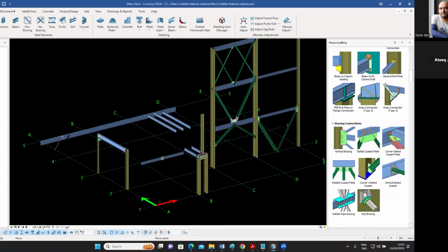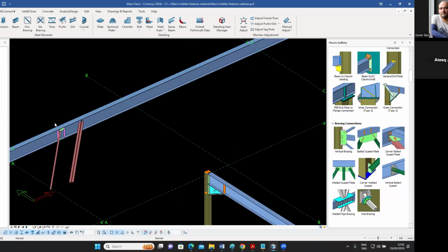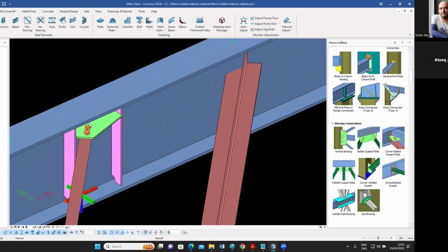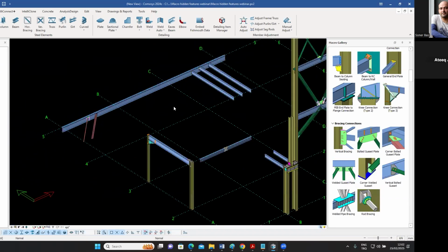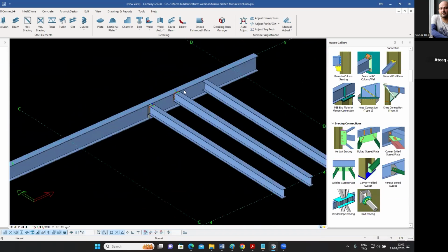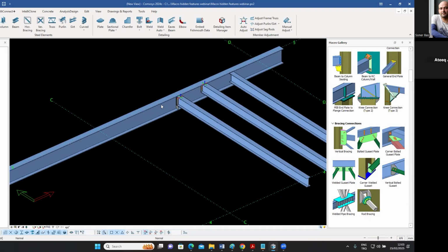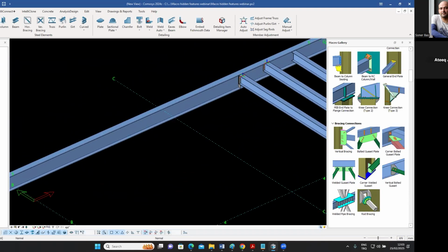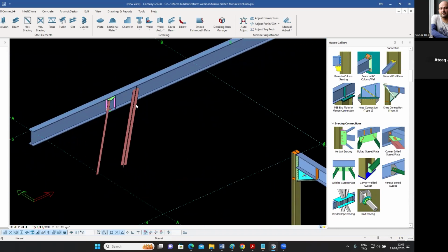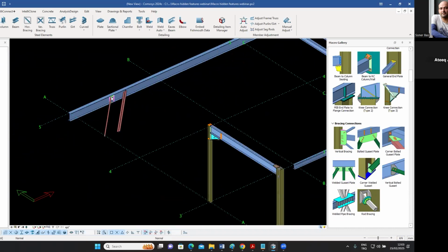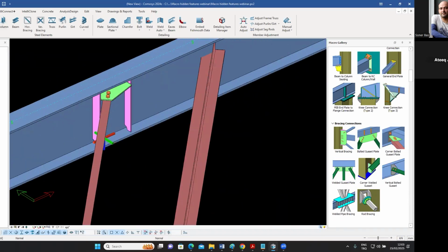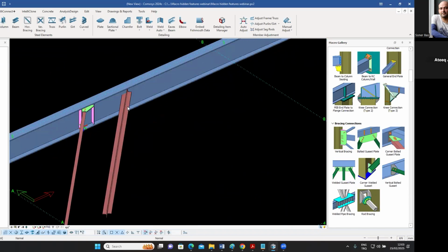So what did we talk about? We talked about the gauge lines. We talked about the edge distances, all coming from project preferences, and the flange angle gauge distances file, and the flange bolting text file. And then we talked about the project preferences file, which gave you the interbolt distances.